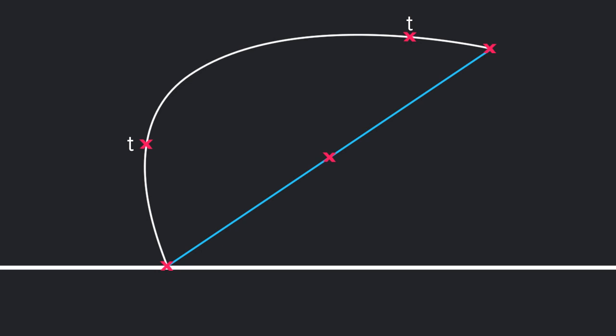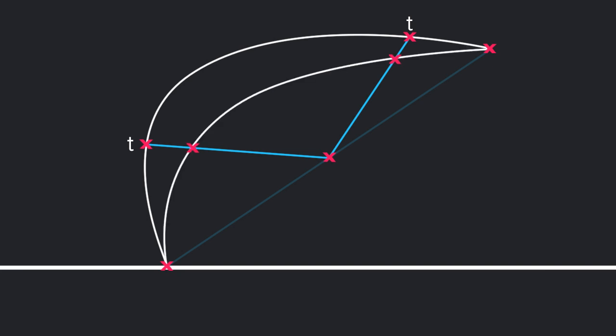And we're also going to locate 2 points in our interpolated curves by evaluating it with 2 parametric values, more or less what I'm showing you in this image. And then we're going to create 2 vectors going from the points in my interpolated curve to our middle point. And then the next thing that I'm going to do is to move these points along those vectors, which then are going to be used to create another interpolated curve.